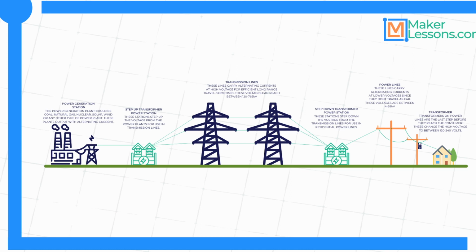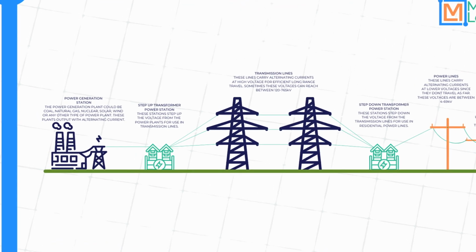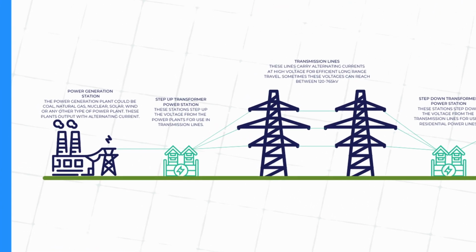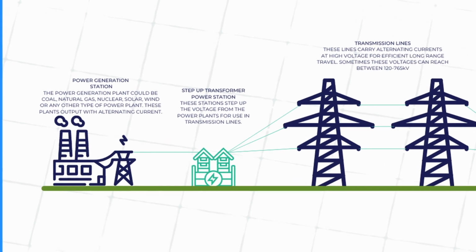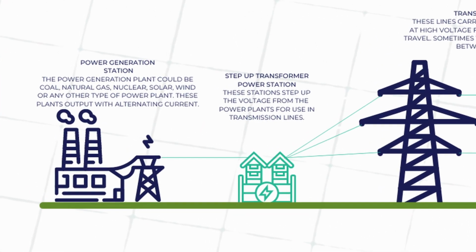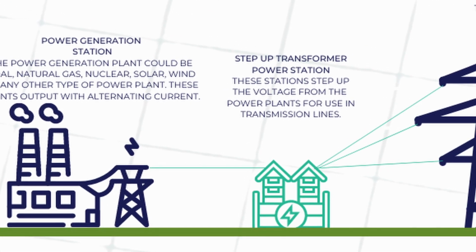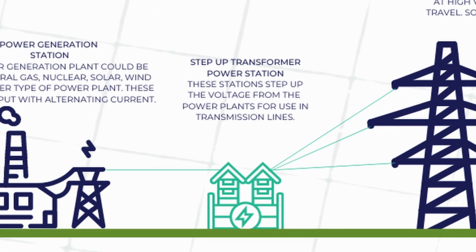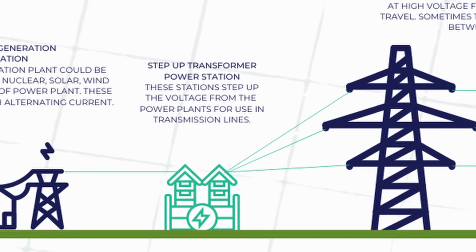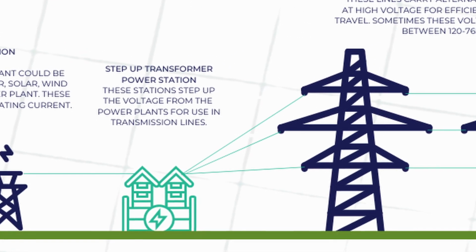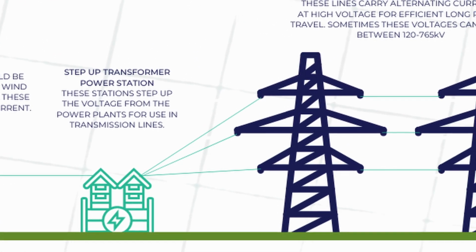With Tesla's patents, Westinghouse worked to perfect the alternating current distribution system. Transformers provided an inexpensive method to step up the voltage of alternating current to several thousands of volts and then back down to usable levels. We needed to do this because at higher voltages, the same power could be transmitted at a much lower current, which meant less power loss due to resistance in the wires.